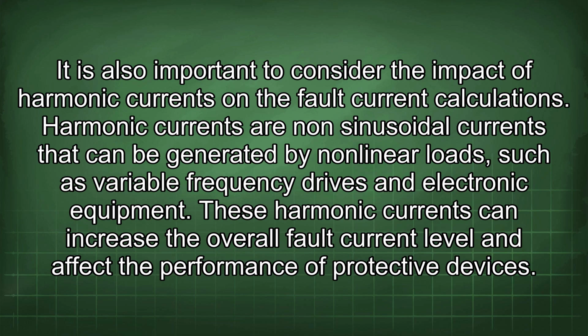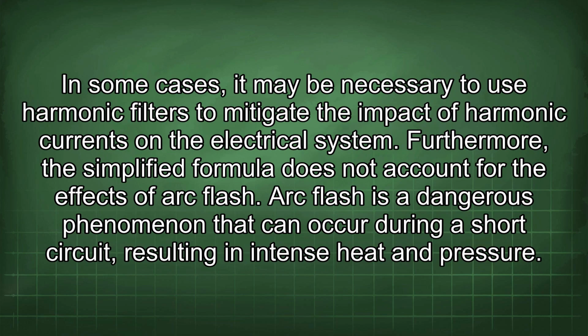It is also important to consider the impact of harmonic currents on the fault current calculations. Harmonic currents are non-sinusoidal currents that can be generated by nonlinear loads such as variable frequency drives and electronic equipment. These harmonic currents can increase the overall fault current level and affect the performance of protective devices. In some cases, it may be necessary to use harmonic filters to mitigate the impact of harmonic currents on the electrical system.